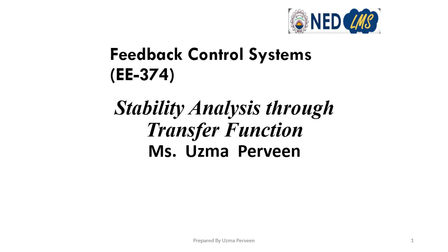The three important factors for a control engineer are steady state response, transient response, and stability. When we consider the transient response, we'll find whether the system is underdamped or overdamped, and when we consider the steady state response, we find the steady state error. We'll find the steady state error in the next few lectures. And the third thing is the stability. But if the system is not stable, then we cannot consider either improving the transient response or finding the steady state error. So it is very important that the system is stable. So first we will find the stability using the transfer function of the system.